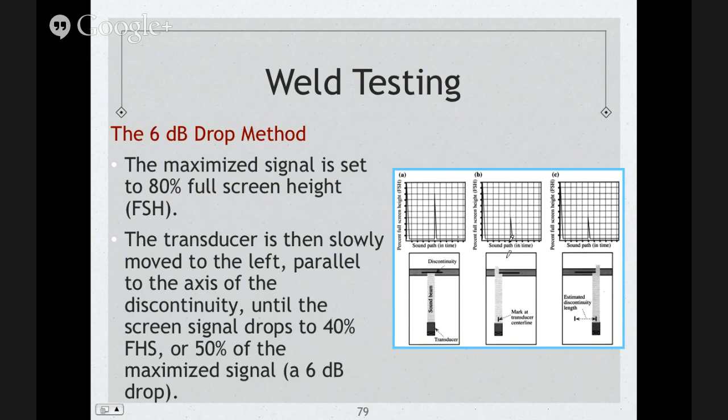Well, if I keep scanning past this point and my indication keeps going down until it dies, then that's okay. I will mark this point. But if after 40% I keep scanning and the indication starts growing again, right? Maybe because it's not like this, and then it comes again flush, right? So maybe when I hit this, I'm going to reflect someplace else.